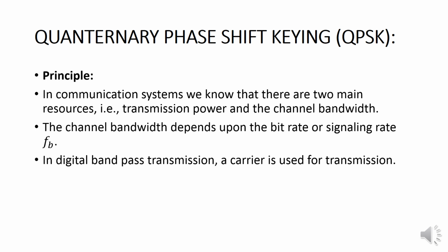The combination of two bits is called a dibit: 00, 01, 10, 11. For each two-bit dibit clocked into the modulator, the signal output changes once, and the rate of change at the output is equal to 1/2 the input bit rate.